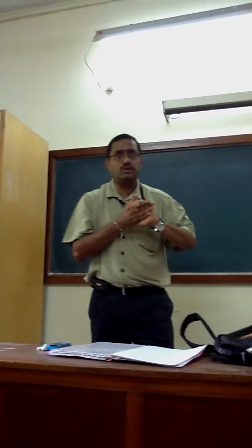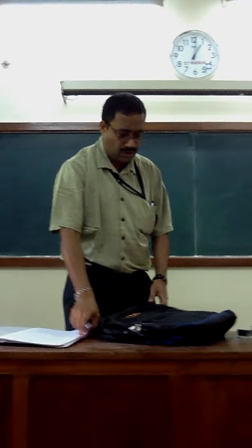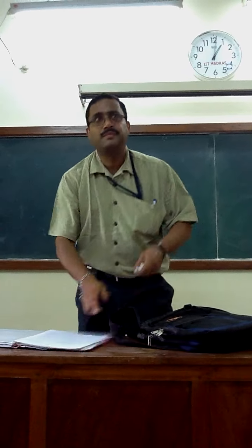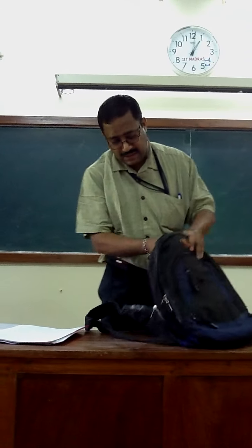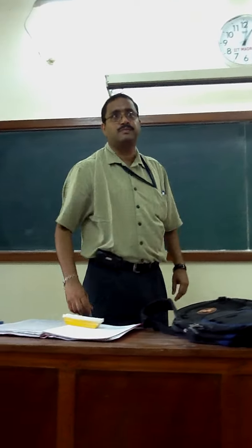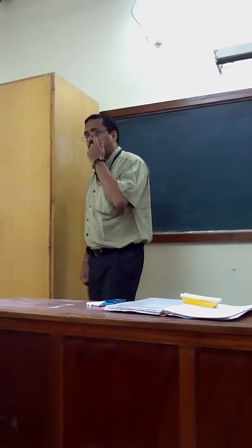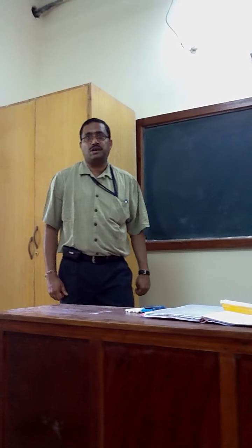Why? Because we do integration. Your answer is correct, but justification has to be there. You are saying property, very correct. But as I said, work done is not a property, because work is nothing but integral P dV, right? Because the integral is not a property.